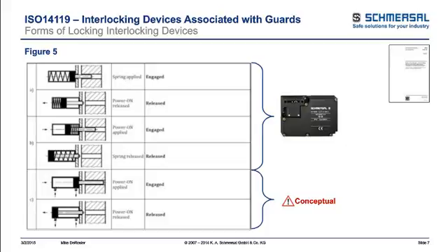ISO 14119 specifically calls out, as you see on the slide, whether you have a spring to lock and energized to unlock, or the next set of pictures, a power to lock and then spring to unlock, or some of the conceptual that some of the manufacturers are working on is a locking methodology where you energize to lock as well as energize to unlock. Those 3 different concepts are clearly discussed in the standard. And when you thought that energize to unlock was the only type of safety device that was allowed, that's not true, as you see per the standard.